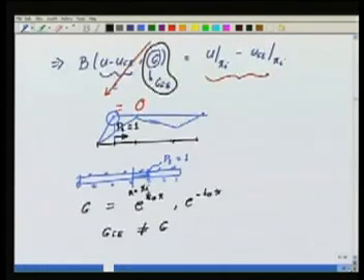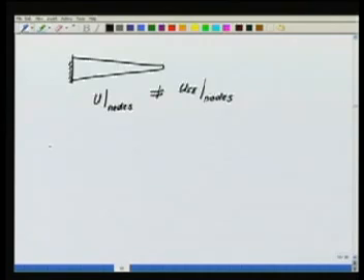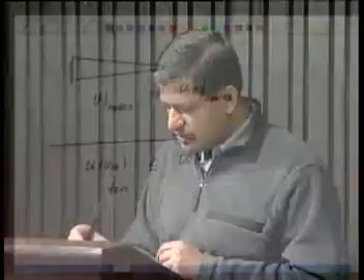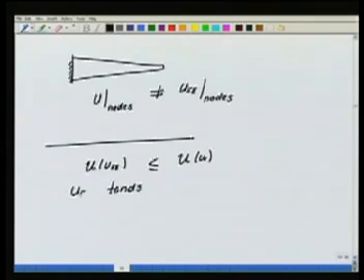So here, we know that U of UFE is less than or equal to U of U exact. So what we say is that the finite element solution reaches or tends to U exact from below, in terms of the strain energy.